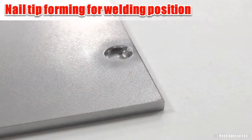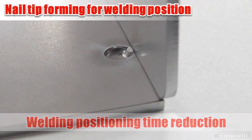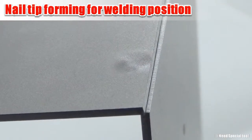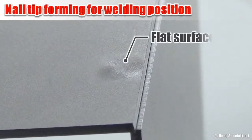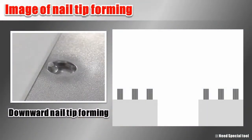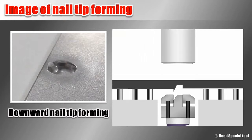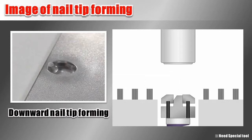This will not only reduce the positioning time of tack welding, but also improve the component accuracy. Also, the back surface is flat, so finishing process is not necessary. The nail tip forming in the blanking process will be done in a single process. Pressed material swells and forms the nail tip shape.